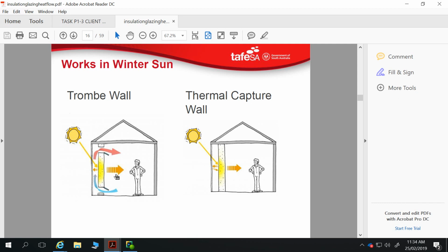Couldn't you use double glazing? You could use double glazing. So double glazing, like your argon filled double glazing, I think the maximum R value you can get out of that is 1.5. So certainly that's better than just single glazing, but it's not as good as a wall, where you can typically get R2.5 to R3. And the expense of it is crazy.